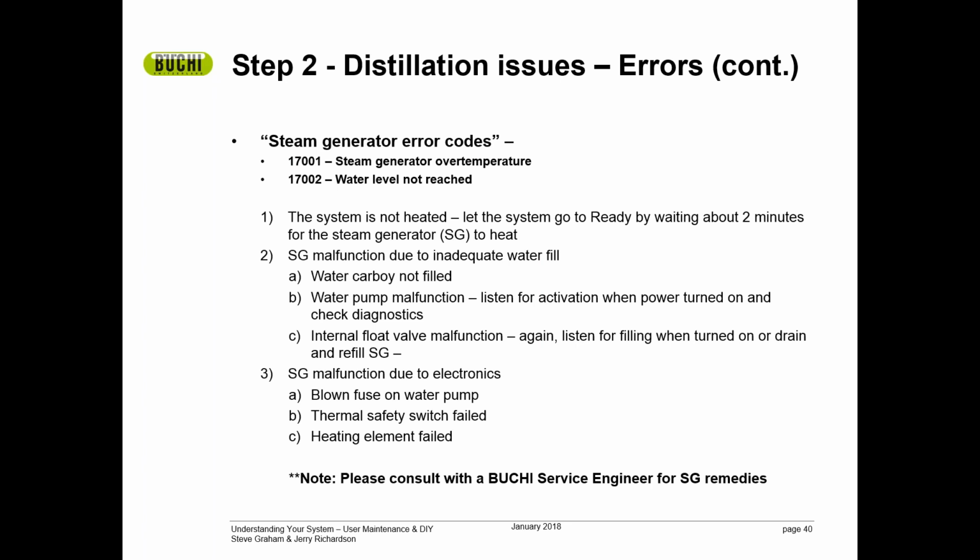If you do not hear the activation of the water pump, then it's highly likely that the water pump itself is bad or the water pump fuse has blown, in which case you need to call Buki and we can replace that water pump for you and you'll be back up and running.